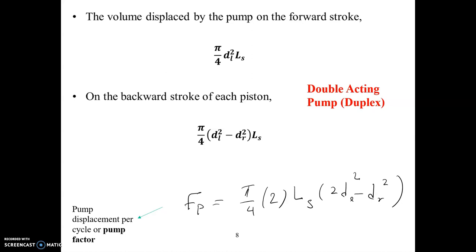One thing you also need to consider is that these pumps are not really 100% efficient. They have some overall efficiency. The overall efficiency of these mud circulating pumps is the multiplication of the mechanical efficiency and the volumetric efficiency. So we define two separate efficiencies.